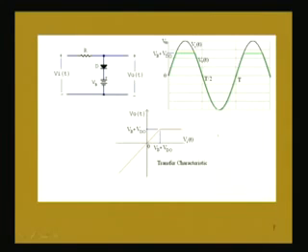Now, for this particular example, if we now plot the transfer characteristics from this output waveform versus input waveform, we see that till the point input voltage is less than Vb plus Vd naught, output and input voltages are equal. So, output and input voltage will be having a linear relationship with a slope 1 like that, as is shown here.